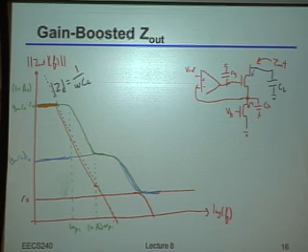Now there's kind of a couple of interesting things happening here. The first is, as I mentioned, I intentionally made this orange curve ever so slightly below the black curve. Okay? The reason for that just intuitively is if you think about it, if you take two impedances in parallel, right, you're always going to get the lower of the two. Now, we have to be a little bit careful when you have imaginary things in there because you can get resonances and stuff like that. But if indeed we make everything stable, meaning we don't have any peaking or anything, you take two impedances, the net impedance will be lower than either one of them individually. Okay? So indeed, that's why I would argue that this line here indeed is ever so slightly below it.